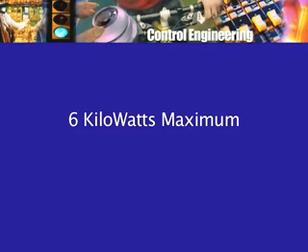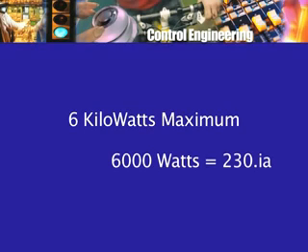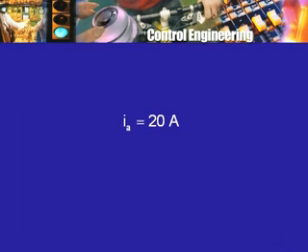Now, is the armature winding expected to carry this kind of a current, 100 amperes? Certainly not for a long time. How do we know that? Well, what was the motor power? The motor power was, let's say, about 6 kilowatts maximum. So that's 6000 watts. That's the maximum motor power, which is equal to the applied voltage 230 into the armature current IA. So 6000 watts equal to 230 volts into how many amps? That will give an answer of maybe about 20 amperes.